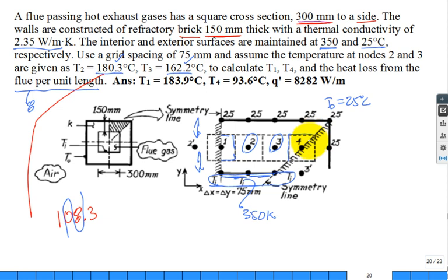All right, so let's do an energy balance for node 1. I would go slow. I'm going to have some flowing in from the 350 into 1, and some flowing in from the 25 into 1. Professor, I know the 25 is the lower temperature. Assume mathematically it's flowing in. That's the best way to write the equations, and it'll do you good. And then flowing in from 2. Do I have any volumetric heat source? No. So let's write our equation.